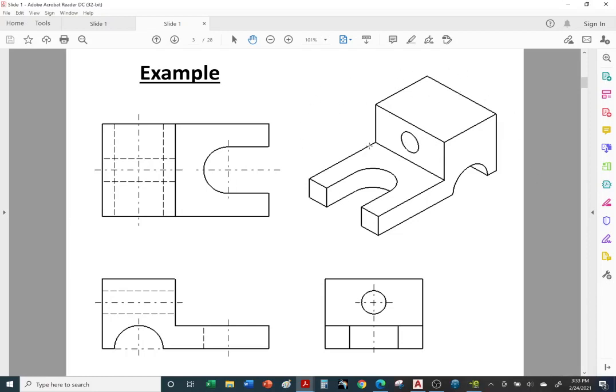Okay, so when we talked about isometric views in the previous chapter, we said imagine putting the isometric view in a glass box, right? Or a cardboard box. So first you draw a box and then you start sketching the part. Just makes it easier. You draw a box with the height, length, and depth, right? You start with the simple box and then you start drawing the object lines. Okay, so once again, these are the object lines. These are around 0.50 or 0.60 millimeters in thickness. And again, your textbook will give you a range of what thickness to use on the lines.